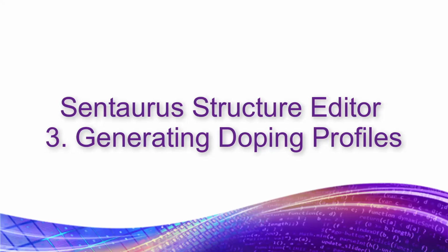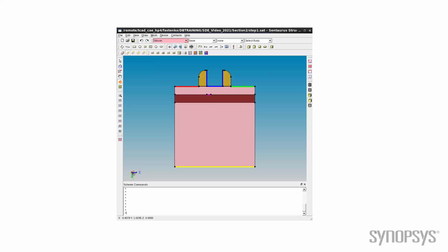Hello and welcome to TCAT Centaurus video tutorial, Centaurus Structure Editor, Section 3, Generating Doping Profiles. In this video, we will use the structure of the 2D PDSOI device that we have created in the previous episode and define doping profiles. In the subsequent video episode, we will go over mesh generation.